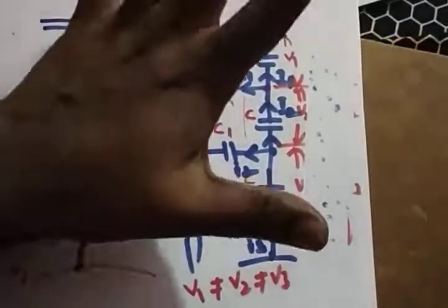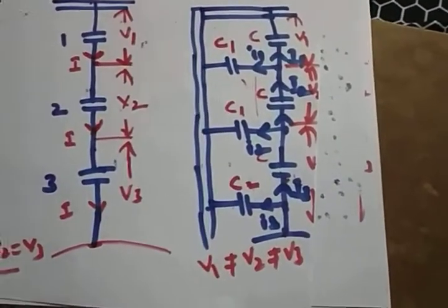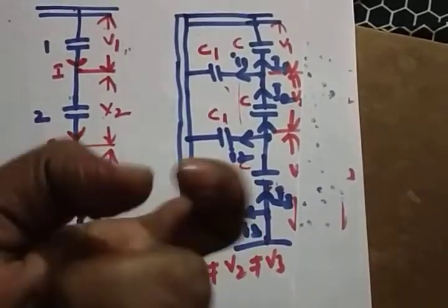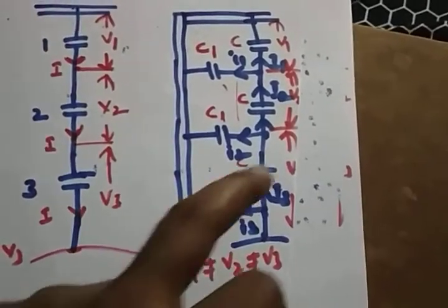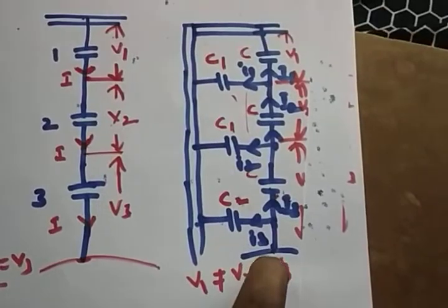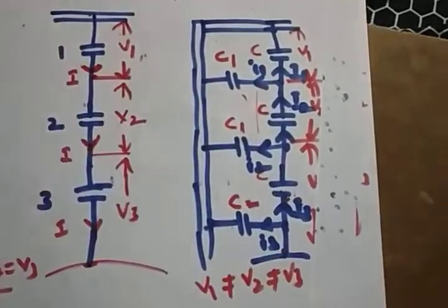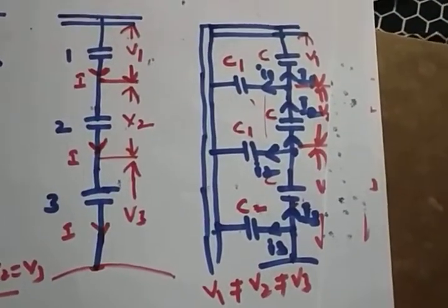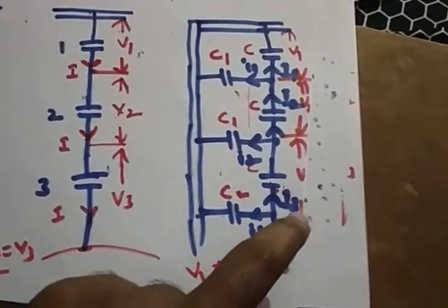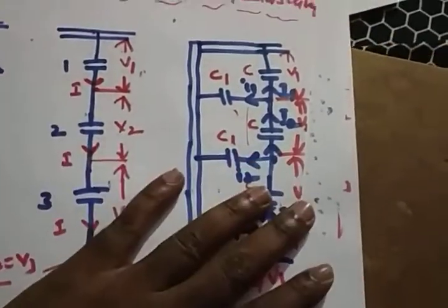If the voltage across the discs is varying, the disc nearest to the conductor has the maximum stress. So there is a high risk of failure from the first disc itself. If it fails, the total string will get damaged.